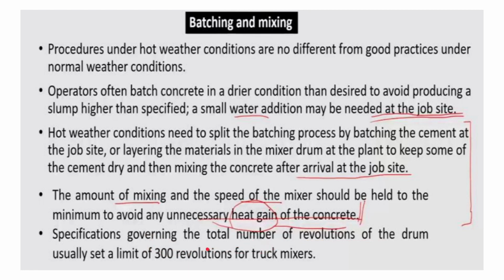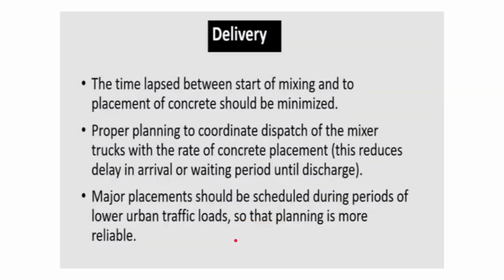Okay, the amount of energy will be more, and that will also result in heat. So let us now come to delivery. How can the delivery be adjusted? The time lapse between the start of mixing and placement of concrete should be minimized. This is one of the factors due to which it's better to batch the cement and mix it at the site instead of at the plant, as we discussed in the last slide.